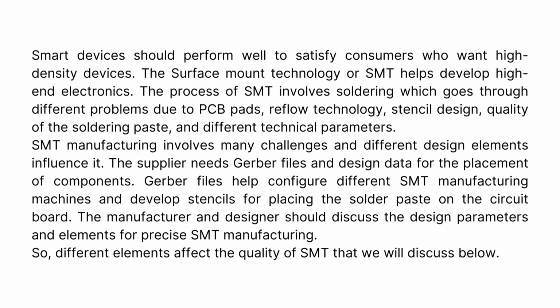The supplier needs Gerber files and design data for the placement of components. Gerber files help configure different SMT manufacturing machines and develop stencils for placing the solder paste on the circuit board. The manufacturer and designer should discuss the design parameters and elements for precise SMT manufacturing. So, different elements affect the quality of SMT, which we will discuss below.